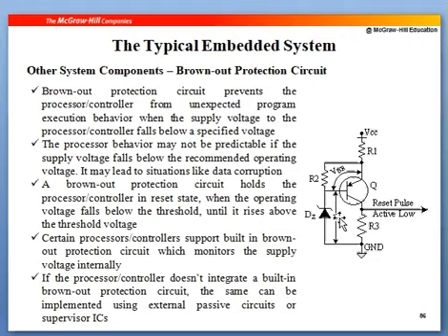In this you will store the predefined threshold with which you will be comparing VCC, and if this predefined threshold voltage is greater than VCC, then you get an active low signal. If not, it will turn on this transistor, and you'll get an active high pulse here always. An active high pulse will not work; an active low pulse works. So this is about the brownout protection circuit.